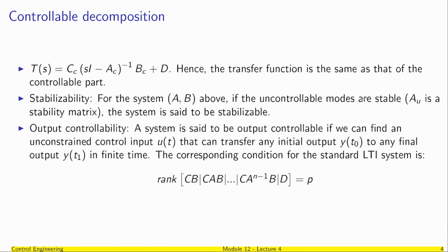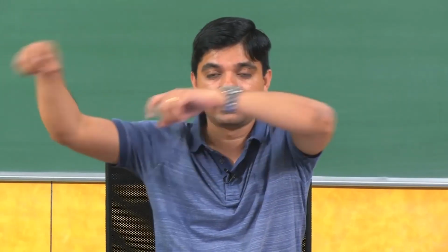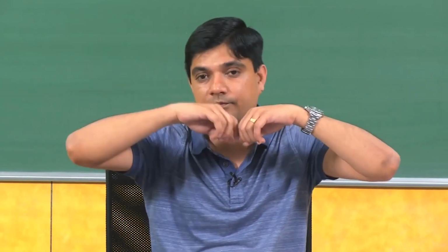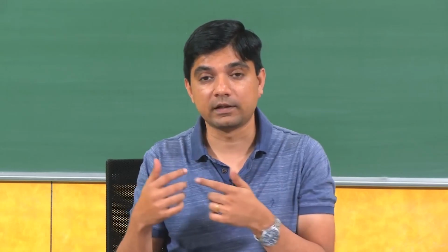And then, as a very small extension to the definition of controllability. So far we have talked about the state going from point A to point B in some finite amount of time, and we are just relaxing that the point B is actually the origin. So, what do I say? Well, I want the output to be controllable, not the states, because typically I have x dot is A x plus B u, y is some C x, sometimes some D times u.